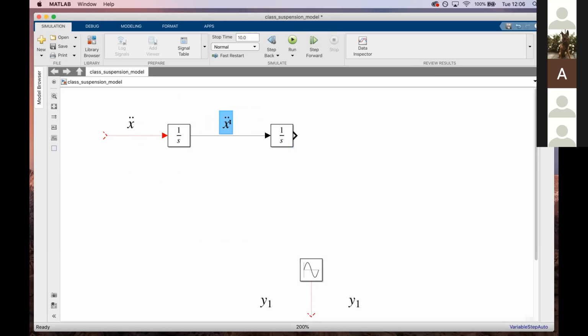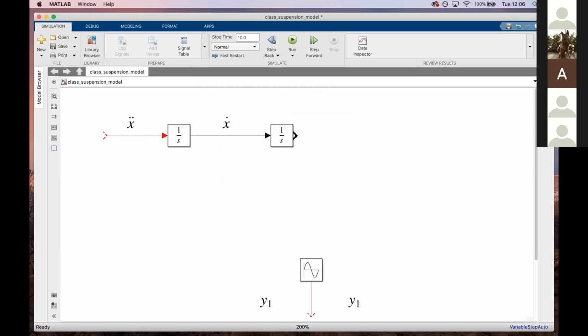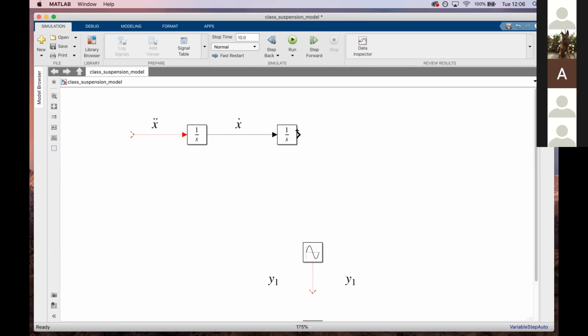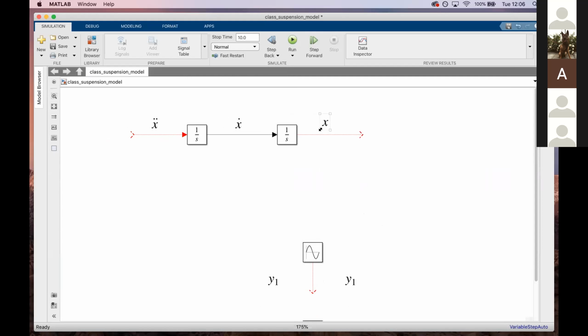And then here, this is going to be x dot. So this is our velocity. And then once we integrate that, that'll be our position. So I say position, but that's the amplitude that we have for the car. Okay, so this is what we're going to be looking at as we're done with our model. And then, once you change your damping and your stiffness, you're going to be looking at X.